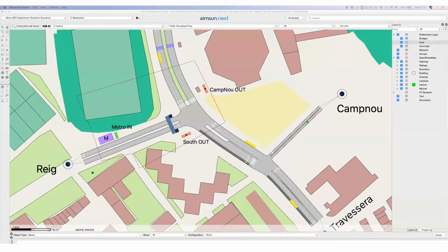Let's now talk about the interaction between pedestrian flows and public transportation services. In Aimsun Next, there are generally two options for how to model this interaction, either by defining origins and destinations at each public transport stop, or by using a new feature that has entered Aimsun Next release 20, which we call the dynamic public transportation assignment. Today I'm going to talk about the latter. You're encouraged to see the documentation for the description of the former approach. So let's dig into this modeling of dynamic public transportation assignment.